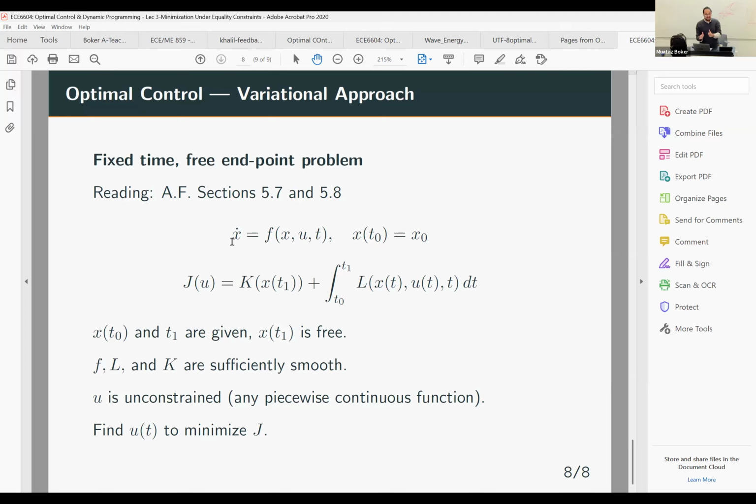The only thing that is given to us, and which makes this problem a little bit interesting, is that t1 is fixed; we don't have up to infinity to do it. We only have a fixed time, which means that t1 being 30 minutes will end up with one u, and t1 being 30 hours may end up with a different one. So the controller is going to depend on t1, all right? So that's the idea here.